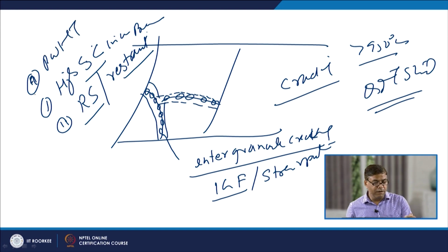So, unfavorable PWHT conditions, the presence of higher stresses or welding under restraint conditions promote first the precipitation and then propagation of the cracks preferentially along the weakened grain boundaries due to the precipitation of these unfavorable carbides.